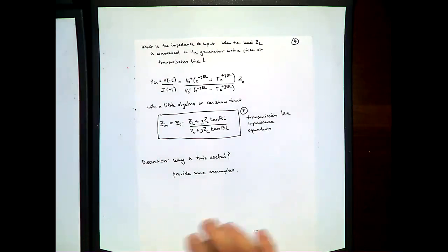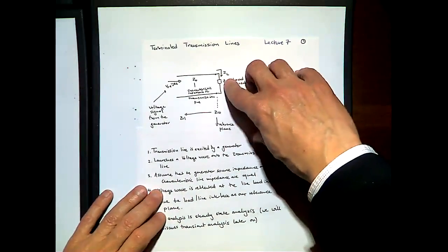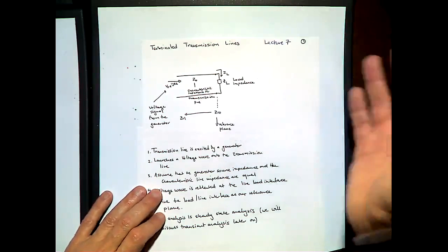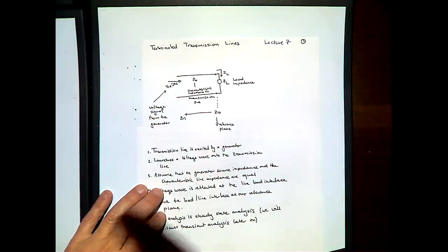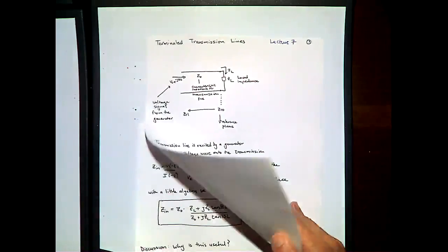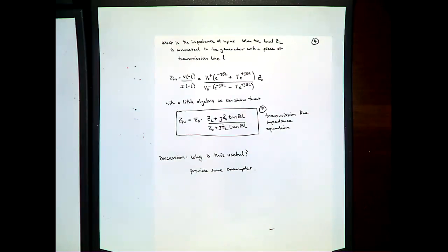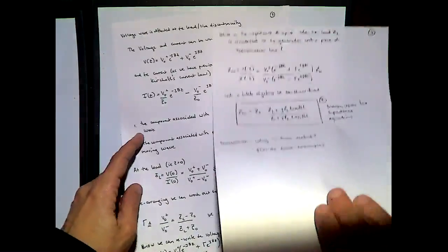Now, what I'll do is, we had this transmission line, so let's go back to it. We had this transmission line. We said that there's a load. It's connected to the generator with a transmission line of a particular characteristic impedance. And if we do that, we can rewrite at any particular location on that transmission line what we expect the impedance looking into that transmission line to be. Right, all I've done is I had my relationship for essentially voltage and currents here.